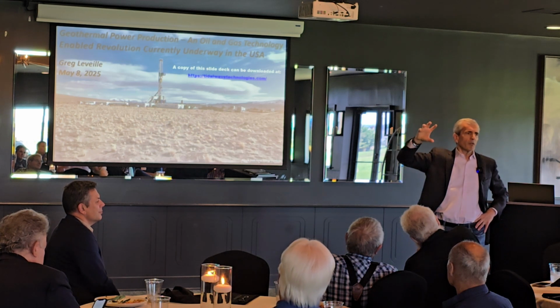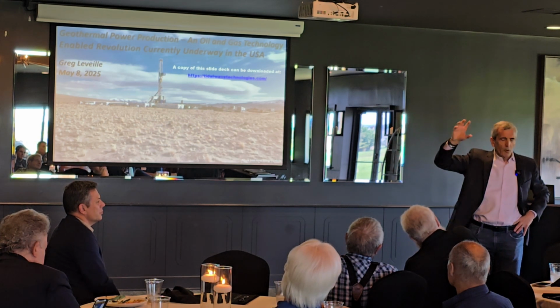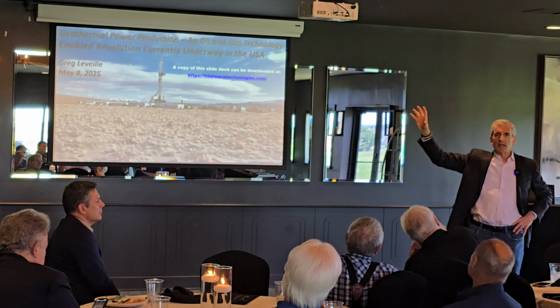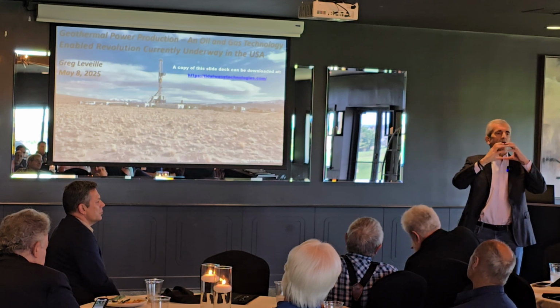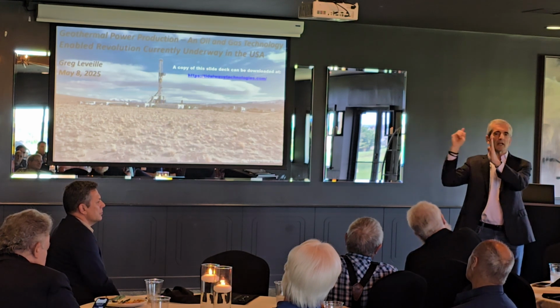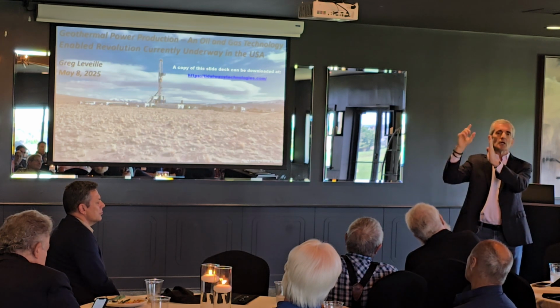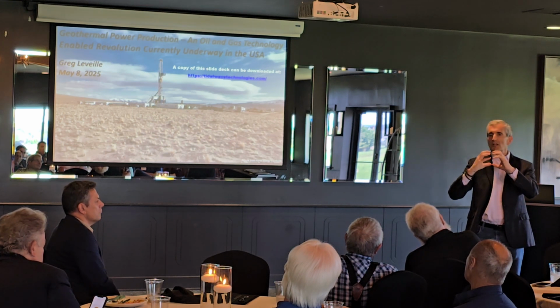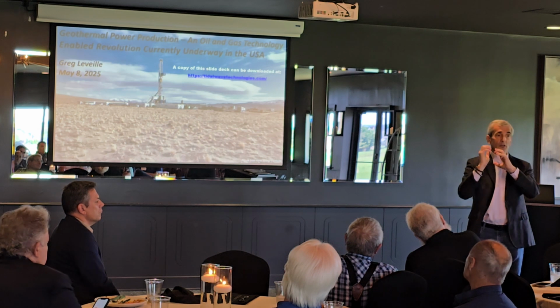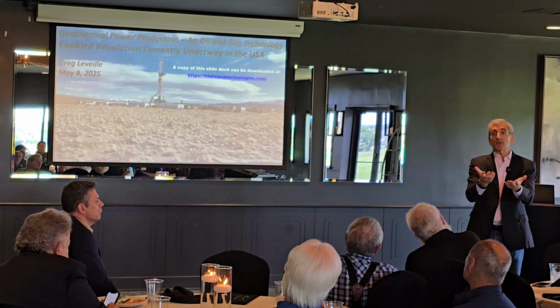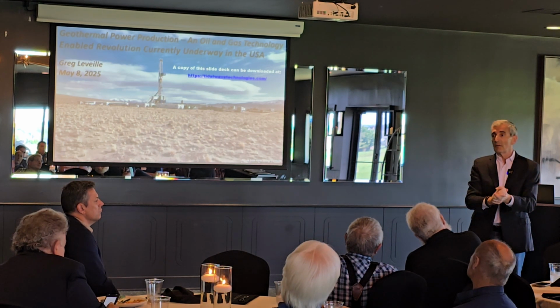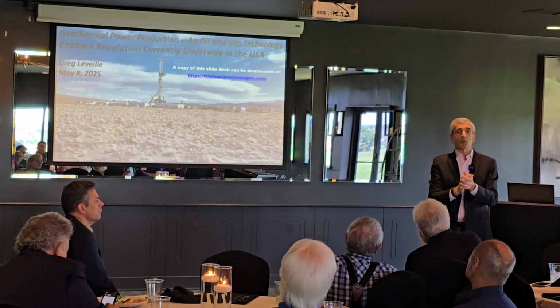You don't have to worry with these, they're called organic Rankine cycle power plants. You actually take the hot fluid through a heat exchanger, and the fluid turning your turbine is actually a hydrocarbon-based fluid. So the fluid from the subsurface never touches the turbine, but you can scale up your piping, or you could scale up those fractures, right? I mean, all of those are bad things. So, yep, chemicals are important.